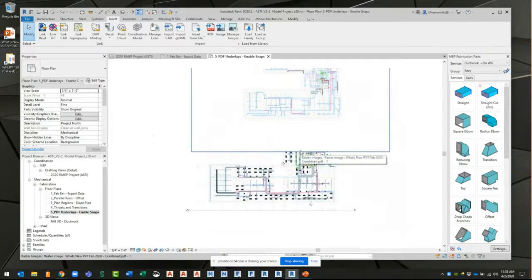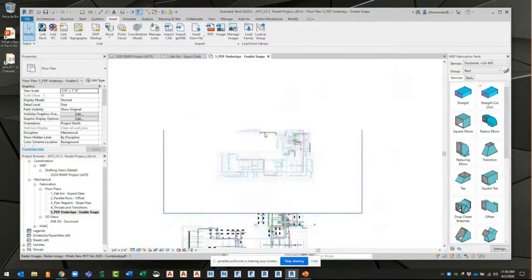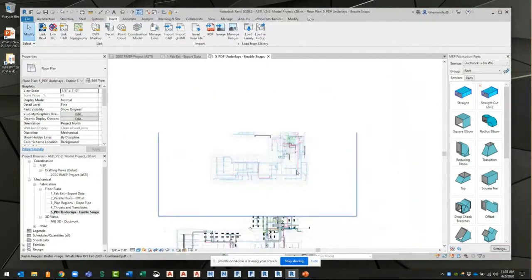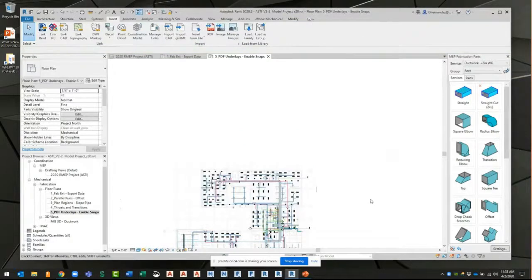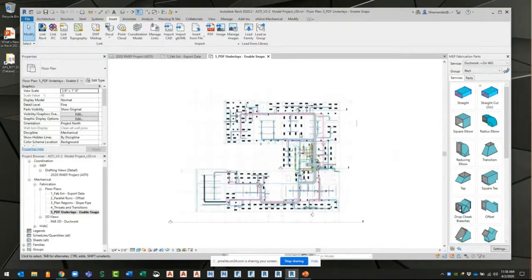Okay, so if you guys are taking any kind of notes, that's a good one. And PDFs, if you're interested in them, remember that they're raster images, because you're going to try to bring it in and it's not going to show up, and you're going to bring it in and bring it in and bring it in, and you have like 20 of them on top of each other, and it's going to go from about 100 megabytes to 300 megabytes. So try not to break it. All right. So be careful when you're bringing in PDFs.